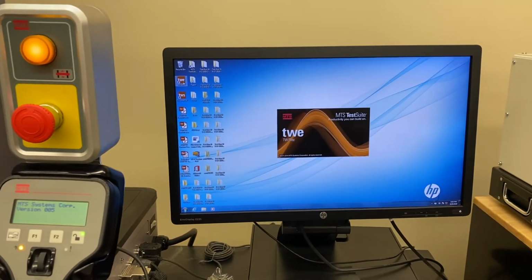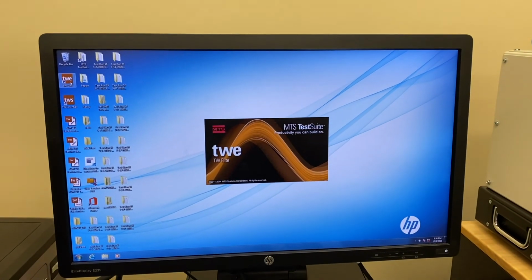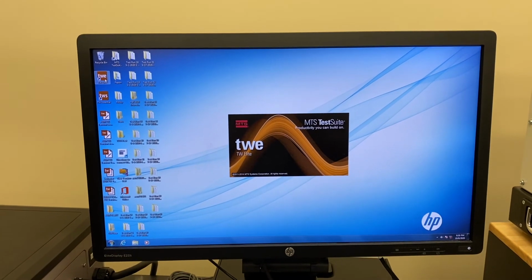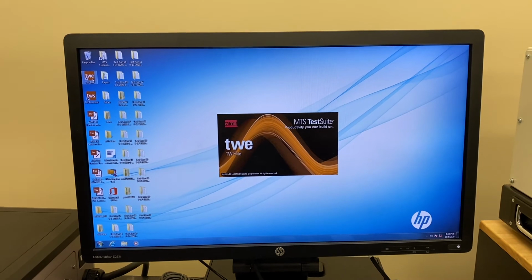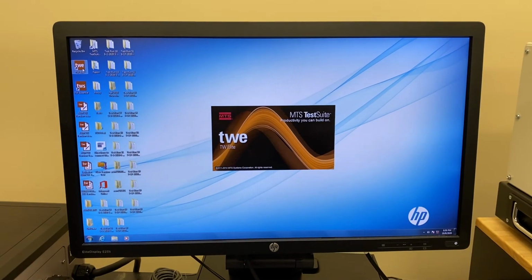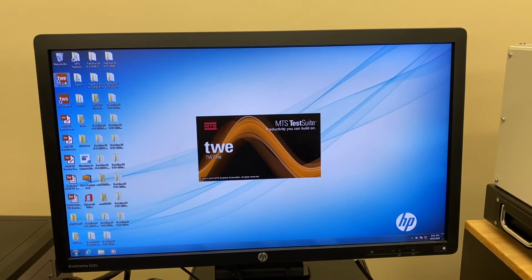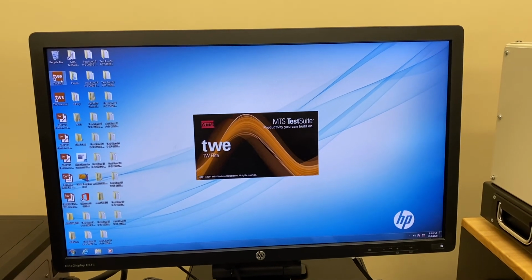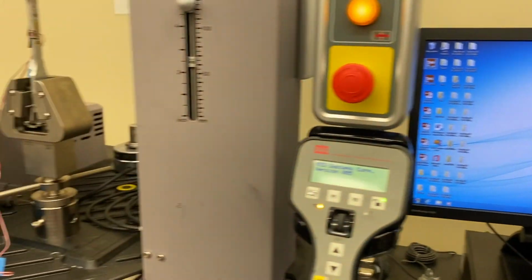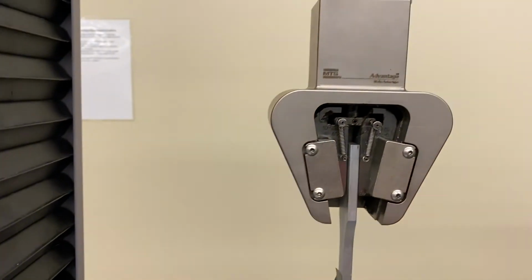So we're going to open our software, and in this case we can use a tension test experiment because we're looking at applying tension to our specimen. As you saw in the specimen we just looked at, there are two strain gauges applied: one in the axial direction, which is our vertical strain gauge at about a 90-degree orientation, and another in the transverse direction, which is placed horizontally at about a 0-degree orientation. While that opens, we'll take a look at the specimen again.